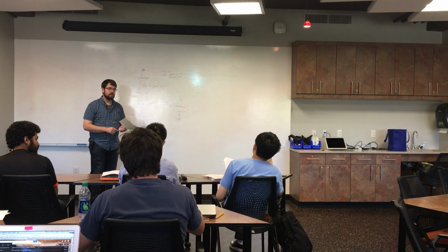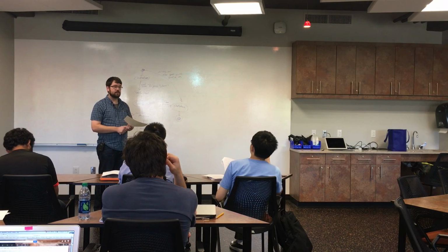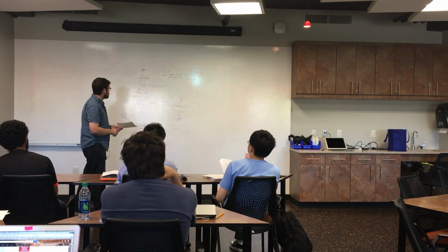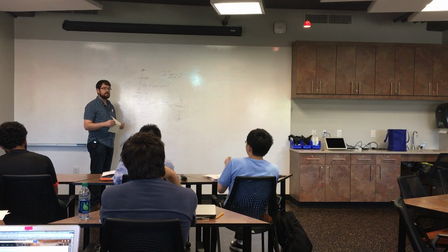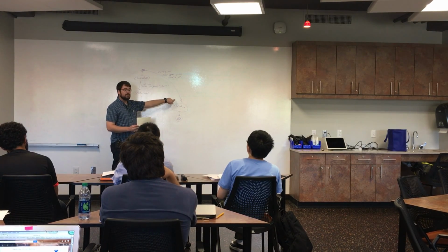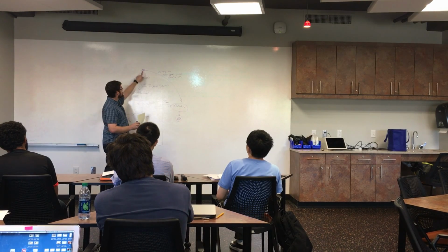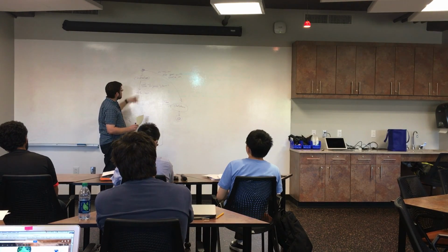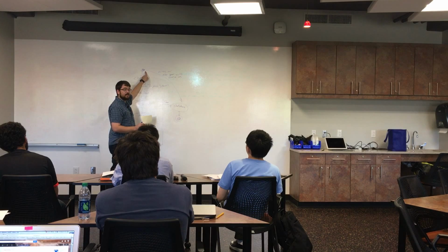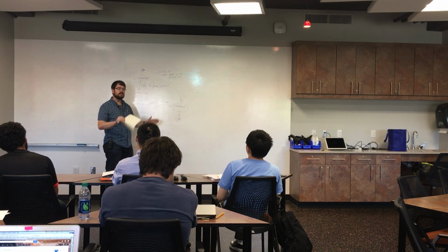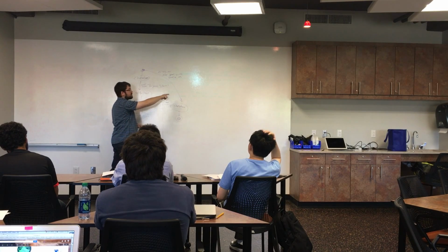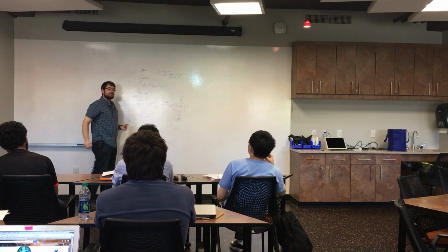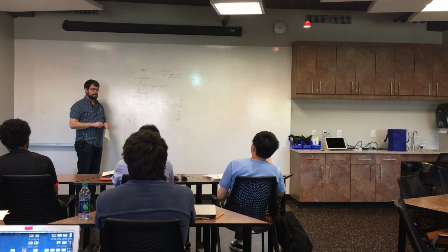But what if there is an error occurring during the scanning state? For example, when you scan the sample, the door is open, and then it needs to be shut down immediately. That's why this is on a parallel branch. Okay. So this is one branch that we're going down and we're running here. Anything else that comes from this dot, it means it's running in parallel at the same time. So if at any time an error occurs or the door is open with the source on, we immediately go to shutdown. So no matter when the door is open?